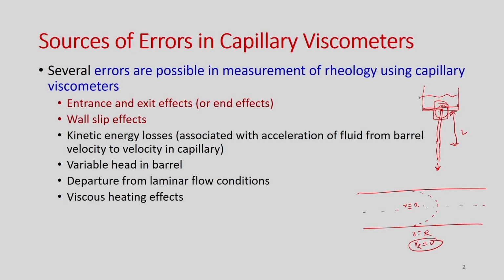That slip velocity occurs because the fluid layers at the wall will be depleted, and because of this depletion, the viscosity of the fluid at the wall would be smaller compared to the bulk viscosity. So, the shear rate would be very much smaller compared to the expected shear rate if there is a slip velocity. So, that is another important one that we are going to check.